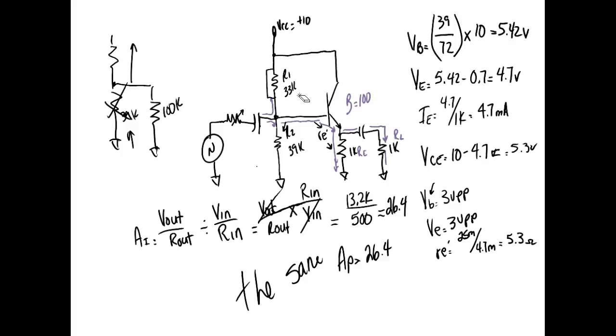VE is going to go real high. VE controls IE. IE is going to go up. IE goes up, transistor moves towards saturation. So this guy will saturate the transistor. Probably go pretty close. The voltage collector to emitter is going to go way down, right?